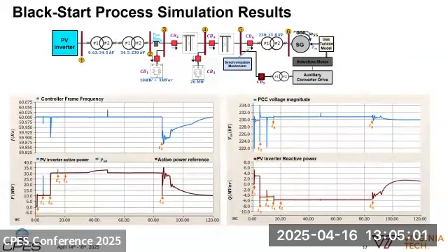So let's take a final look at the complete simulation results of the black start process. After circuit breaker 6 is closed and the power balance synchronization is enabled, the automatic power sharing between PV and SG can be realized by their PF droop. The gas turbine governor steps up the power reference, so the SG starts to inject active power into the black start network, which alleviates the under-frequency and over-voltage condition, bringing the PCC voltage and frequency closer to nominal value. Another thing is that the frequency and voltage of the system can be maintained under all switching actions and all the grid side variation.